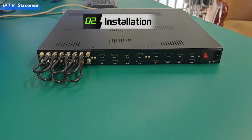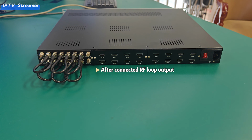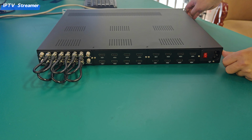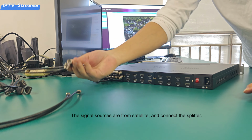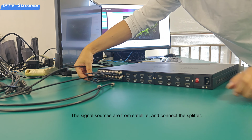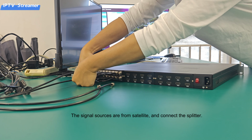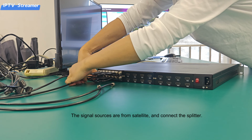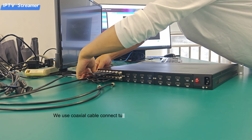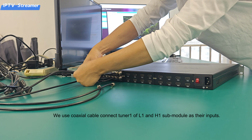Installation. Step 1. Connect satellite source. After connecting the RF loop output, let's connect the satellite signal. The signal sources are from satellite, and connect the splitter. We use coaxial cable to connect tuner 1 of L1 and H1 submodule as their inputs.